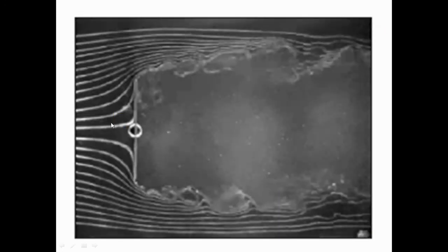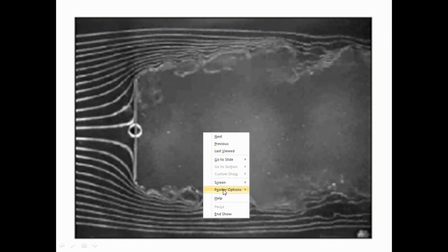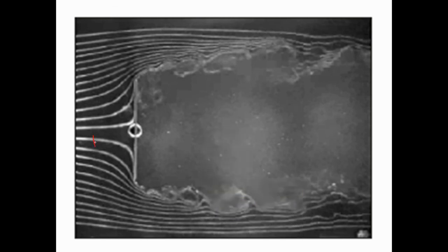And again here you have a high pressure region, as we have seen recently, and then the low pressure. So there will be more drag, with the flow getting separated from here. These objects will have a larger drag coefficient, CD being about 1.2.